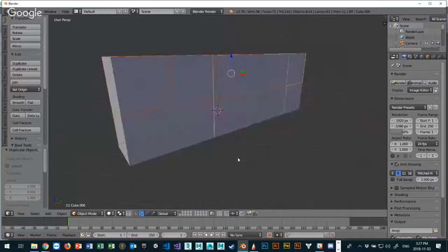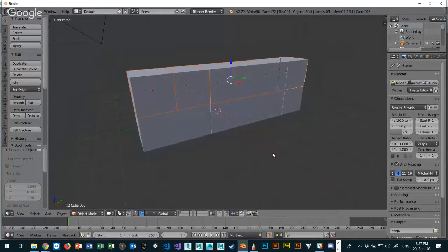It doesn't take long to do this kind of stuff. But this is the first part of navigating Blender. You need to understand how to navigate Blender inside the main viewport. This here where my mouse is right now is the main viewport in Blender. I'll take a couple more minutes to do it. Shouldn't take you long.